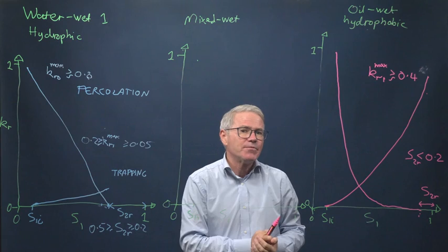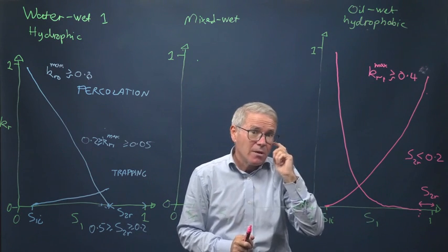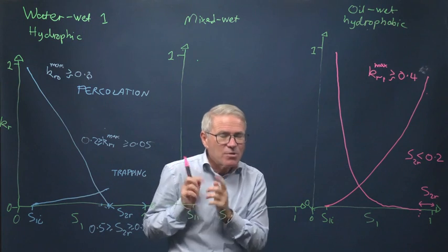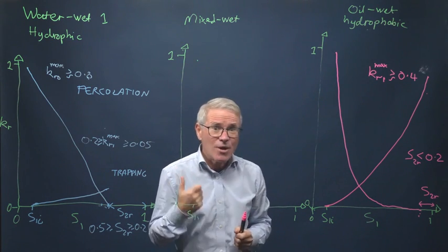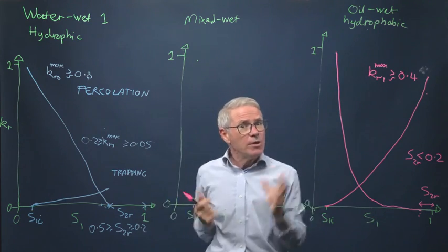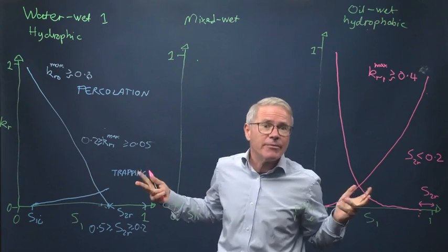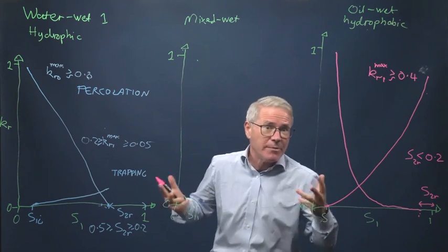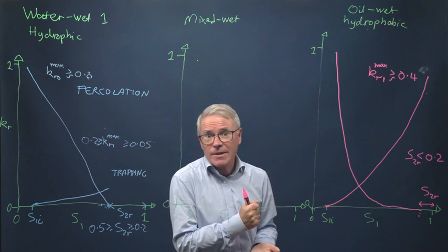blocked them off. And this is really quite extreme, because if you think about it, when I talked about quantifying conductance, I said how conductance goes as area squared, radius to the power 4. And don't get hung up by the fact, oh, that was only for a circular tube. I'm sure if it's something different, it's going to be different. Yeah, there's going to be a different coefficient. You know, it's not pi by 8. It's going to be something else. But the area squared stays the same. It's always the same. That's the physics.